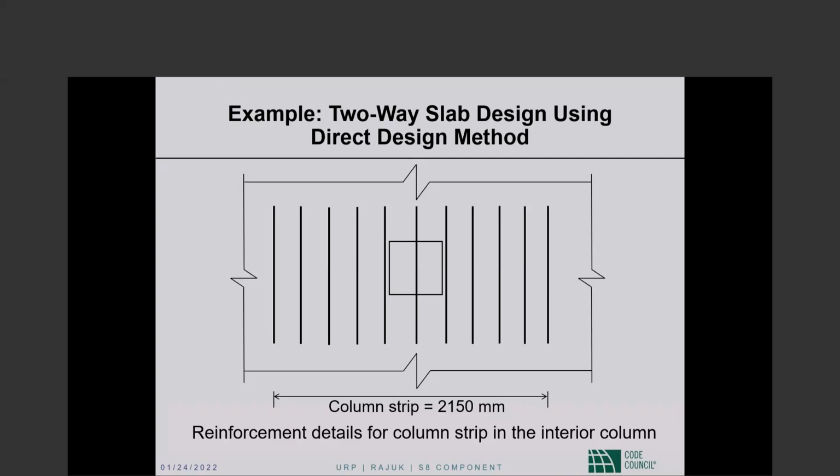It can be 100% or I guess another number. So anyhow, when we are talking about 85% of the moment being carried by the beam, it is 85% of the column strip moment, not 85% of the design strip moment. I hope that clarifies what you are asking.